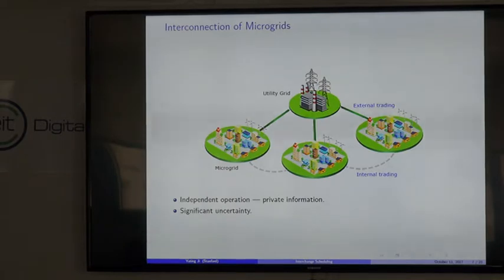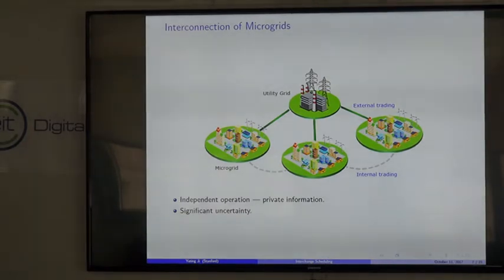When we go down to the resource resolution, there is a new emerging technology called microgrids. Those are on a very small scale. Let's say a university can operate on its own if it's disconnected from the big grid. It has its own generation and its own demand. They can satisfy their own demand by local generation if they want. For this small scale, scheduling between each other is also important, because there might be excess generation, or some peak load that cannot be satisfied on your own.